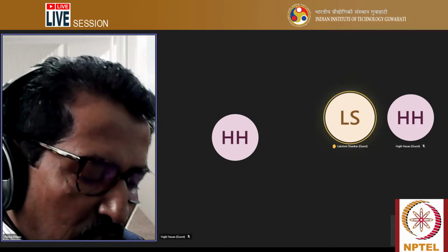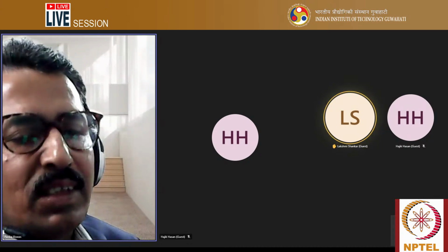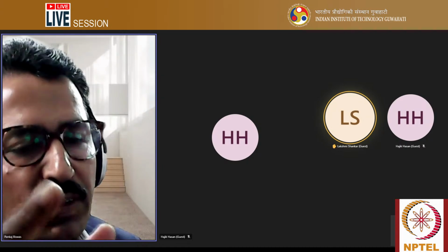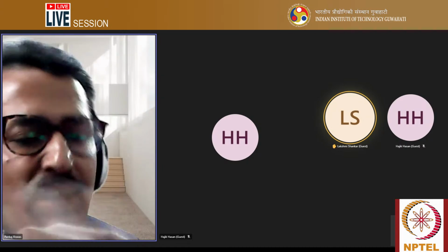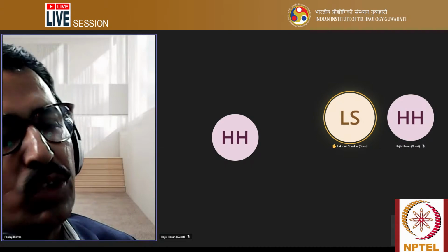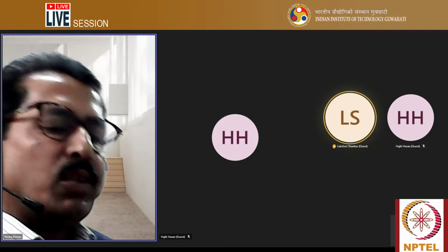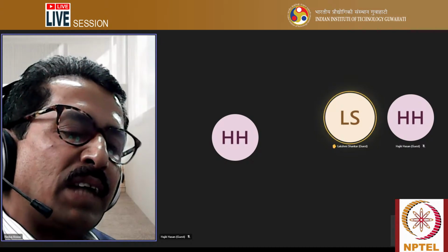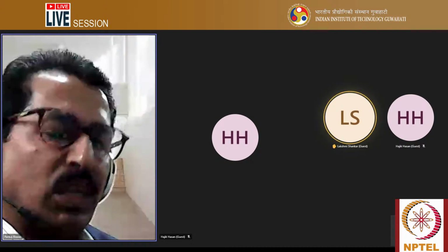Once the cellulosic compound burns, it creates carbon monoxide and hydrogen. That hydrogen creates a problem called hydrogen embrittlement, which acts as a cold cracking phenomenon in the weld.